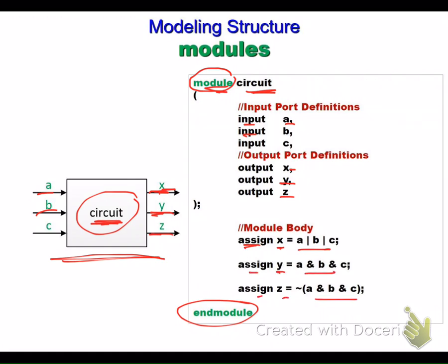The question is, there is no wire here. I did not define X and Y and Z as a wire, as I just mentioned. Am I deceiving you or what? The issue is that if you did not define those variables as a wire in advance, but you define them as an output, that's fine. That should be fine. You have to have a description for that signal before you begin to assign it.